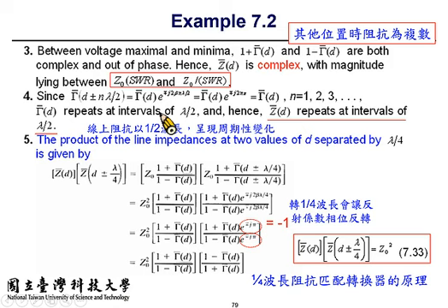Okay? So keep this in mind. This thing is minus 1, and this thing is minus 1 as well. So the second half of the equation becomes 1 minus gamma D over 1 plus gamma D, and the first one is 1 plus gamma D over 1 minus gamma D. So the denominator and numerator cancel each other. You end up with the product of the two equal to the square of the characteristic impedance.